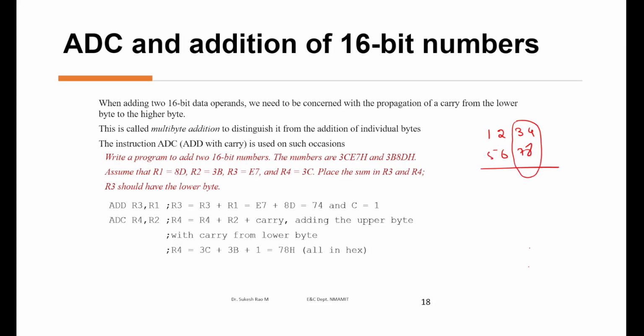The difference is that I will use the usual add instruction for the lower part. The upper set of numbers should be added with add with carry, because obviously I should consider any carry out from the lower addition. That's why add with carry is there.